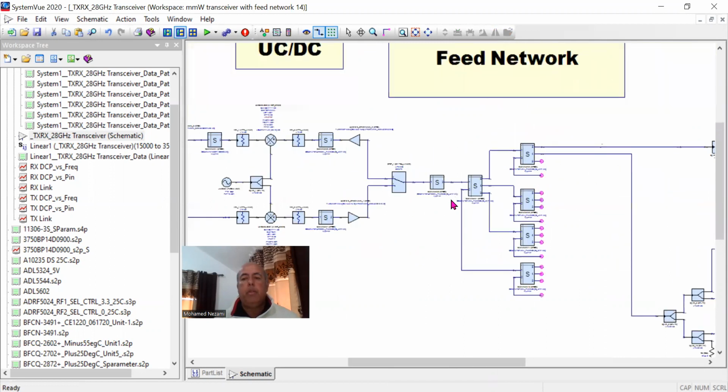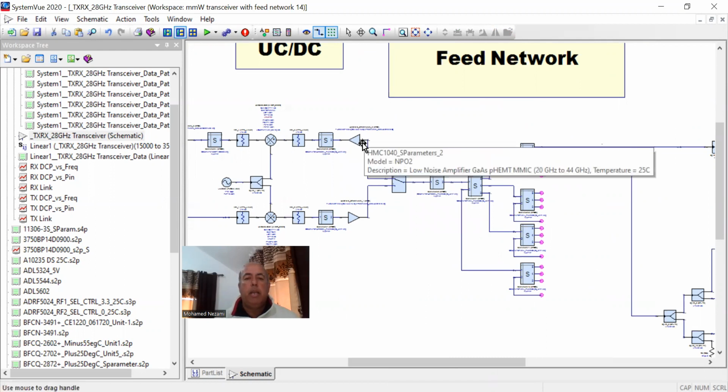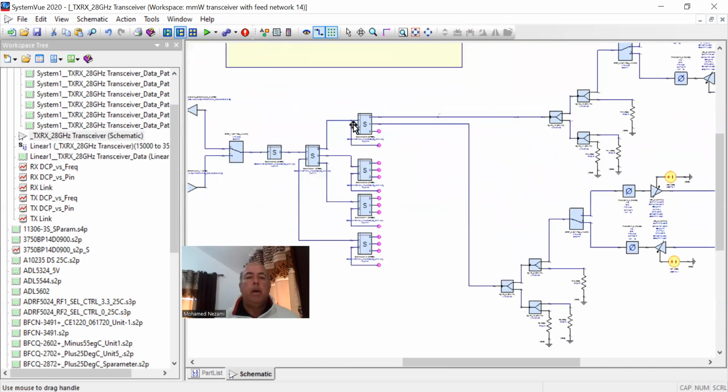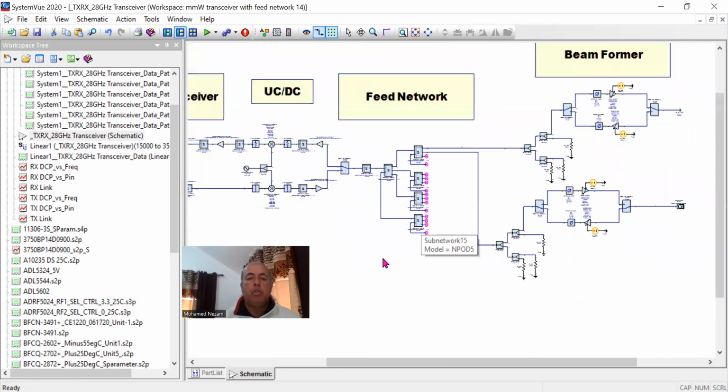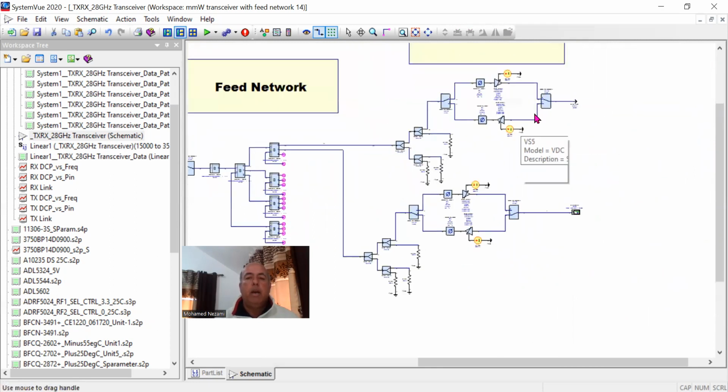And then I moved the transmit receive switch here and utilized a front end LNA and a PA for mmWave frequencies. Okay, and then after that, of course, you have to drive the array. And in this case, as I will show a little later, I'm going to need to split 16 ways because I'm driving 16 transmitters and 16 transmit receive TR antennas. So that's what I'm doing here: I split 16 ways. This is a passive distribution to the antennas. Okay. And then I have the beamformer.